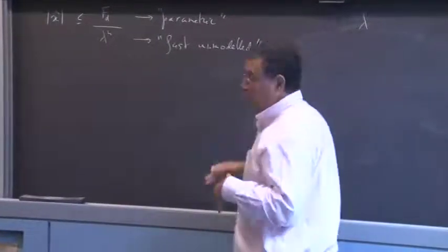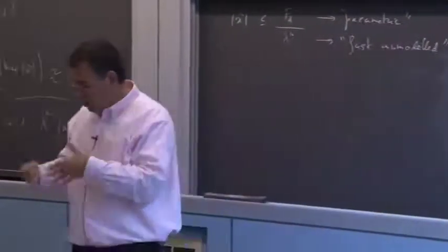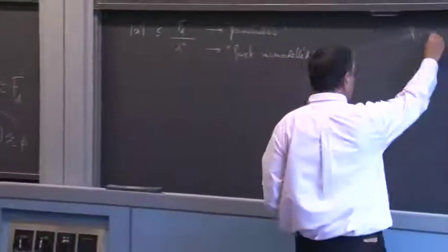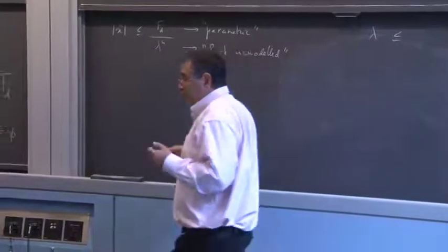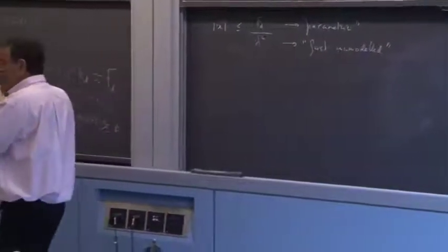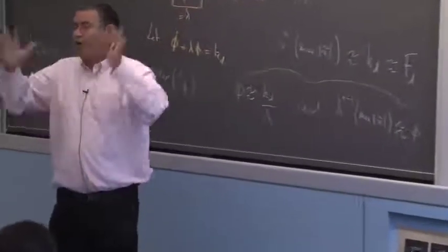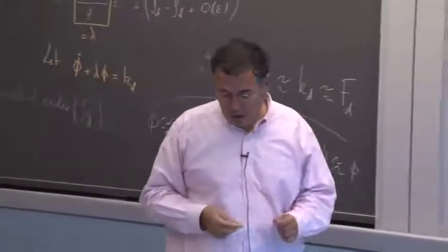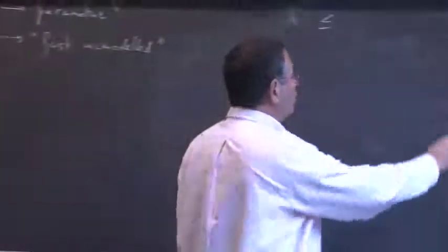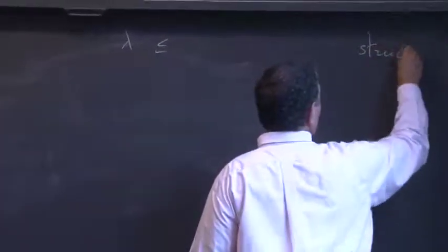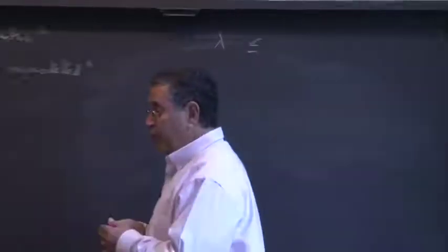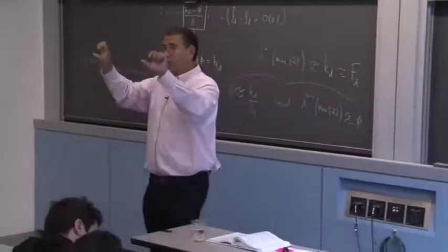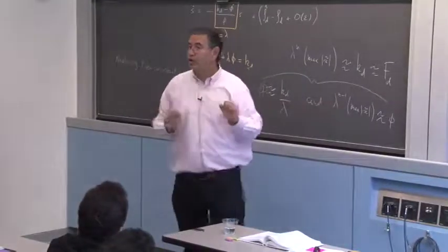So let's see what lambda is possibly limited by. This discussion would be the same in a linear control course. Here it's more within the mechanical engineering context, but it could be general. Lambda is limited by a number of things, which have to do with the fact that you want to win a factor of 3 or 5 over the unmodeled fast dynamics. So what could there be? You could have, for instance, structural unmodeled dynamics. For instance, your motor is going through a shaft, and this assumed the shaft was rigid, and of course, there's always some flexibility.